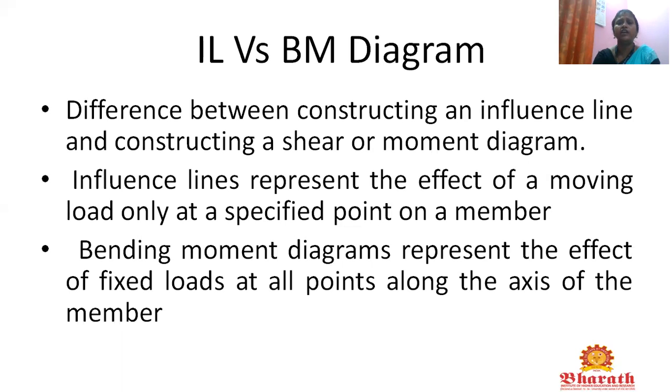Next, we are going to see influence line diagram versus bending moment diagram. So what is the difference? The difference between constructing an influence line and constructing a shear force or bending moment diagram: an influence line represents the effect of moving loads only at a specified point on a member, while a bending moment diagram represents the effects of fixed load at all points along the axis of the member.